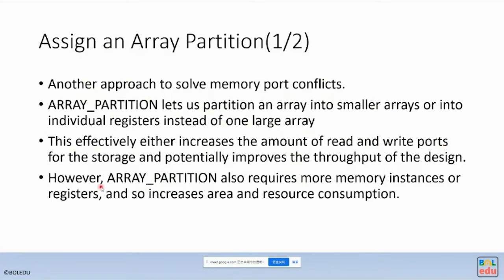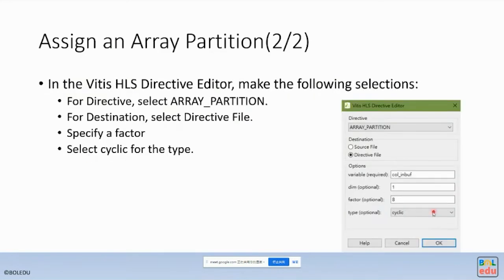Okay, however, the array partition requires more memory instances or registers, so it increases the area or resource utilization. Yes. And so how to do this in HLS? We can also do this in the directive editor. So we choose array partition. Yes. And you can specify the factor and the type.